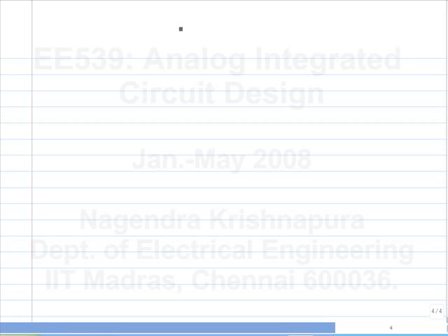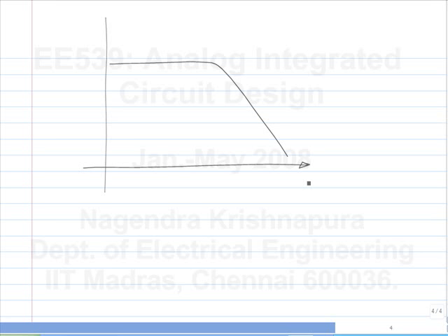Okay. Now, the frequency response is nothing but the steady state response to a sinusoid, okay, at different frequencies. Now, it tends to instability means the poles will start becoming complex and then probably start moving towards the imaginary axis. Now, if you have a set of poles like this, the natural response consists of oscillations at this frequency, right?